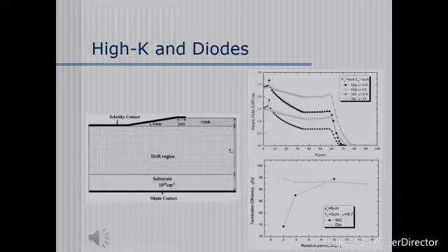Semiconductors with large band gaps are very useful for future power devices. For the past 20 years, huge improvements have been made to the doping, processing, and growth of high-power devices. The problem is that unlike its theoretical results, the breakdown voltage is always smaller than estimated because the structure of the semiconductor used is not uniform, and there is crowding of the electric field at the corner of the electrode. When using high-power technology, the breakdown voltage of the dielectric might be reached before the semiconductor's.